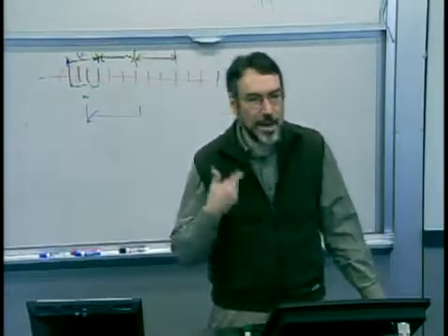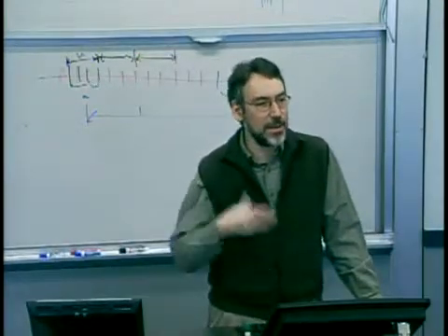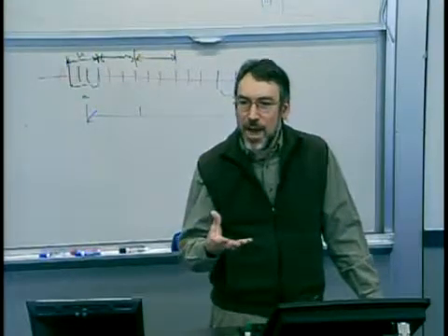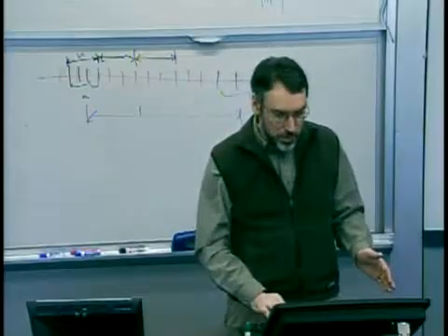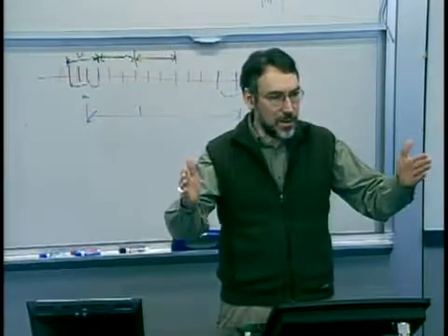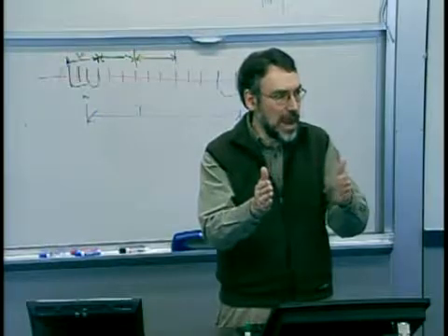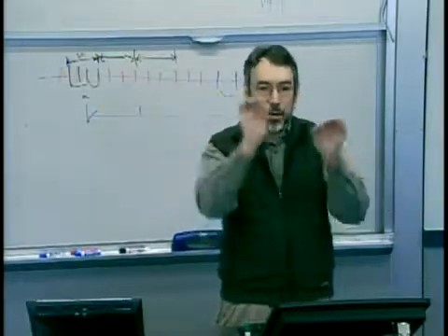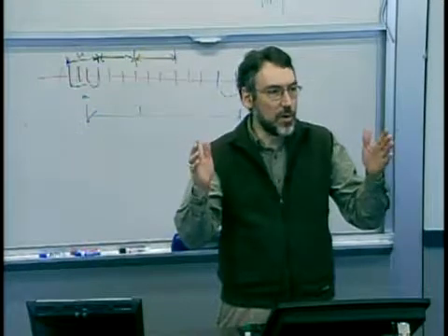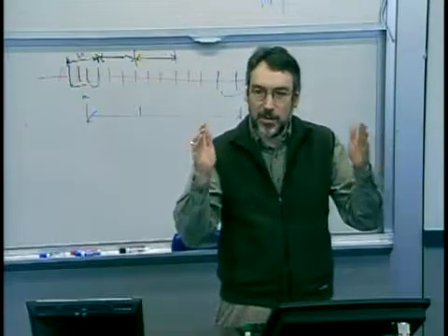Essentially, a very nice canonical way of talking about how far apart your spec limits are compared to your distribution, how good your underlying process is compared to your spec limits, is this notion of process capability, or Cp.